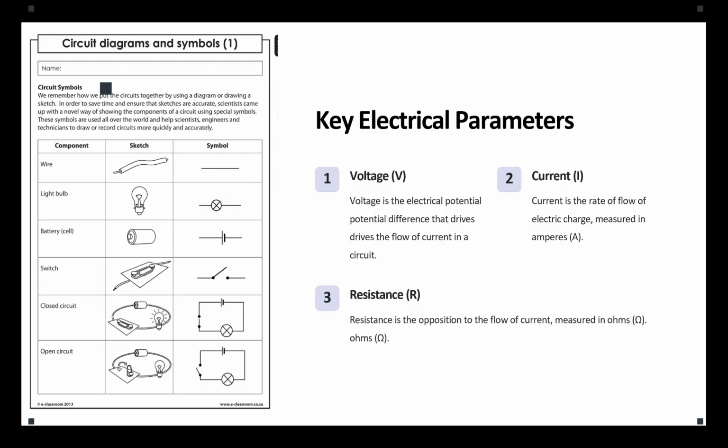Now let's restate that fact. That's true. When you have a DC component or DC circuit, capacitors behave as an open circuit, and the inductor behaves as a short circuit. So basically, they are not working in your circuit as a component. They are either open circuit or short circuit.